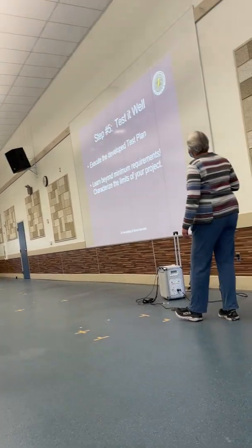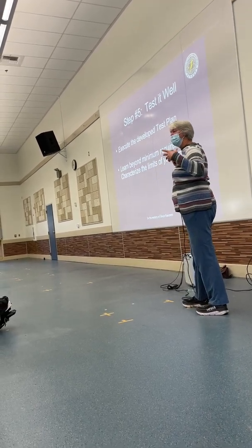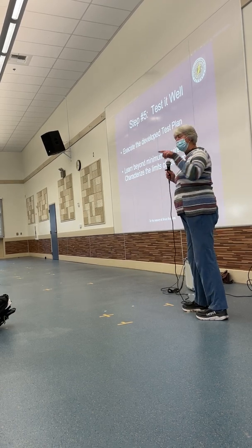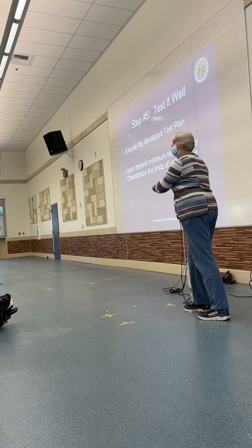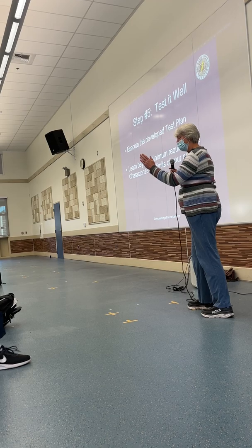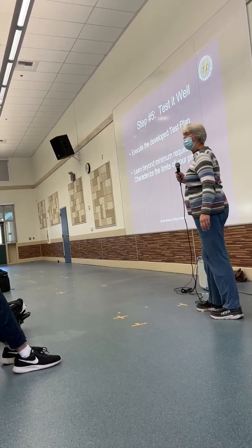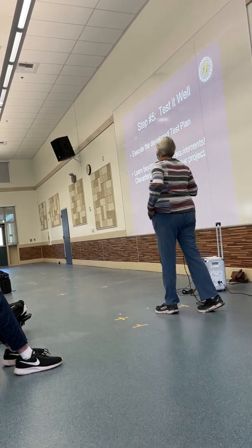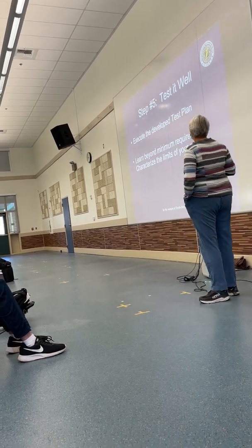Test it. Yes, test it well. Execute the developed test plan. Actually, figure out that you're going to test it in multiple circumstances. And you don't want to just test to the minimum requirements. You actually want to know how far till it breaks. I mean, you don't want to break your beautiful prototype, but you'd like to know that it isn't, that you can hold 35, but 35.1 and boom, it goes down, because the first shock you take, it's gonna fall apart on you. So figure out what the actual margins are to where it breaks.